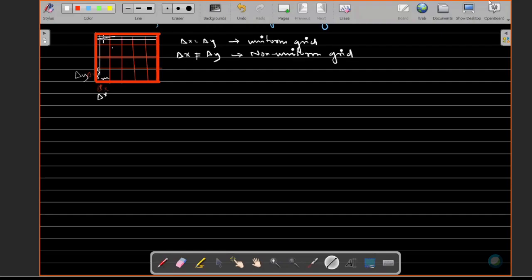You should be able to capture the gradients at those locations. So you convert them into small cells, and the rest of the central core domain, where there is no large change, you can keep as it is.